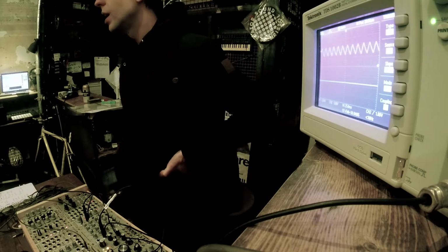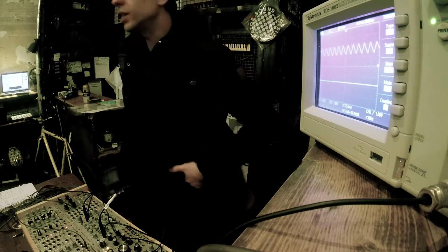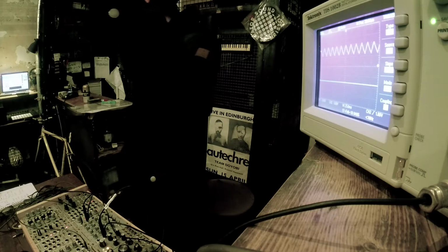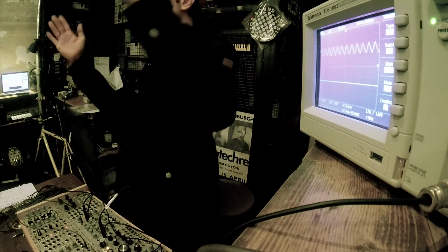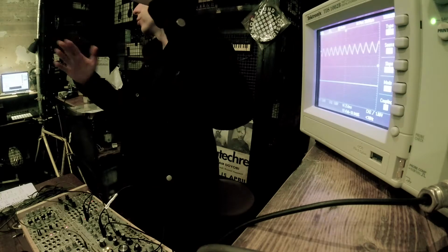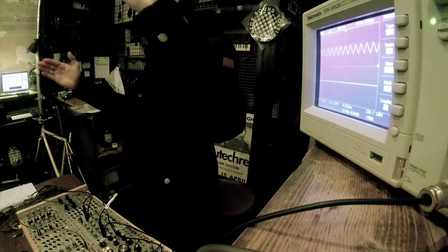That's the thing, because as you're changing the cutoff frequency, what you expect is that a certain range of frequencies should not be affected. You see, if I move my filter between 1K and 500 Hertz, I don't expect that the energy at 100 Hertz should change at all.